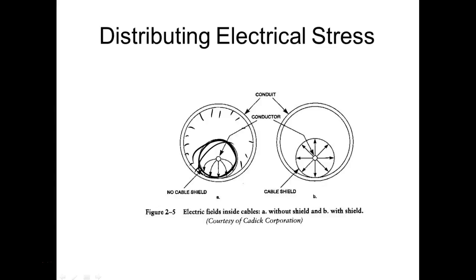That side part of the insulator could break down. So we could actually get current flow through there, and once you get current flow, then you create those carbon paths through there, and then you got a big problem, right? You understand? So when we start getting into these high voltage cables, they try to do something that makes that insulator see this no matter what you're up against.